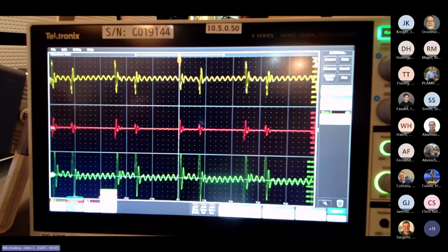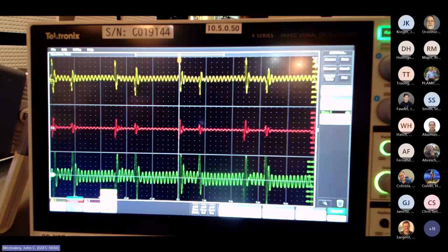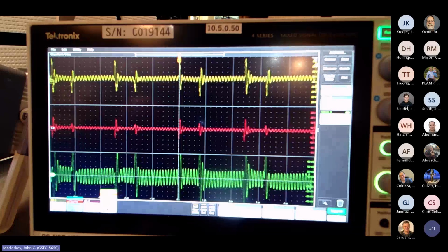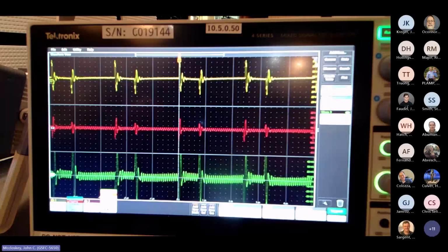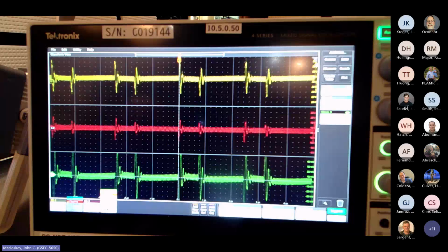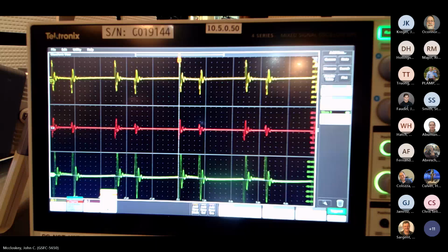But then if you hit 6 dB above the pre-calibrated current limit on the high frequency plateau, then you will stop. You will dwell for the preset amount of time, 1 second or 3 seconds or whatever you've set, and then go to the next frequency.